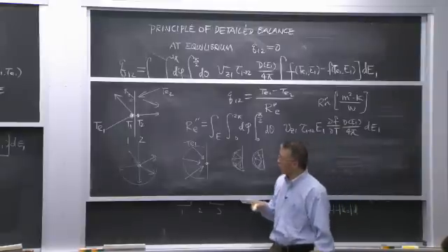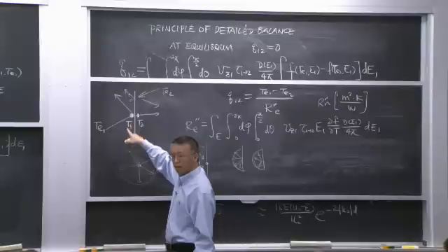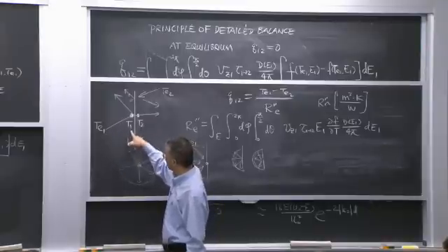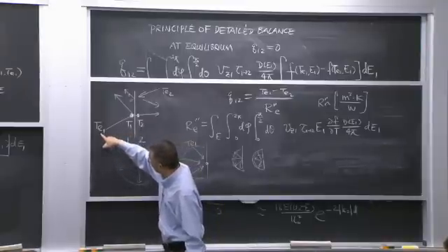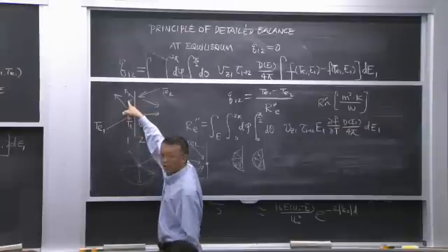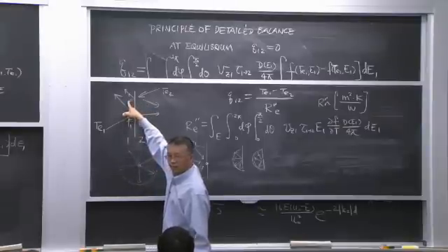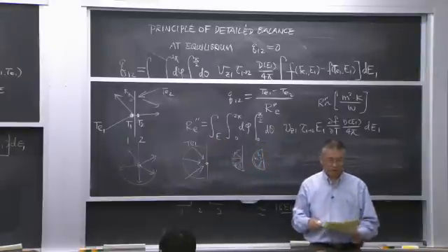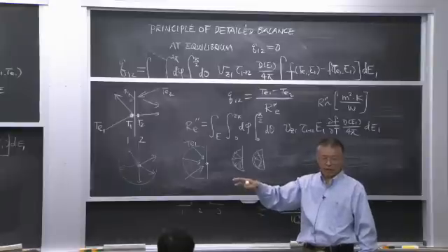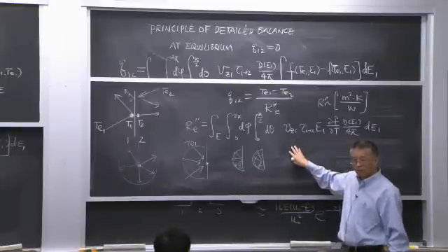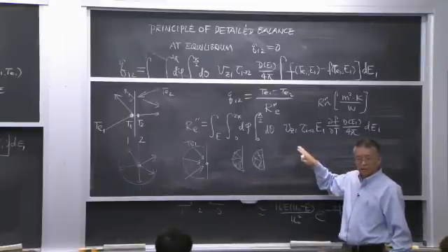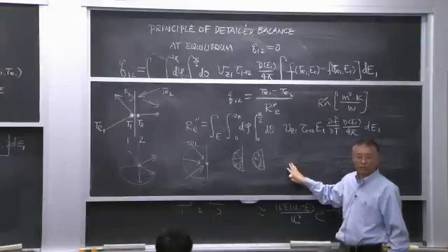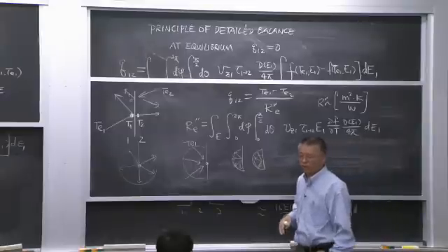Right? So if you do an equivalent temperature, T1 and T2, and redo your energy balance, it will be different, because this T1 will clearly depend not only on the temperature coming in, but also on what is transmitted from the other side. So you will have to write the relation at the end, your expression. That's in the book. I'm not going to rewrite it. You get a different thermal boundary resistance, and that one, in the limit when transmission is 1, is 0. Okay? I wrote that. And people typically don't know it.